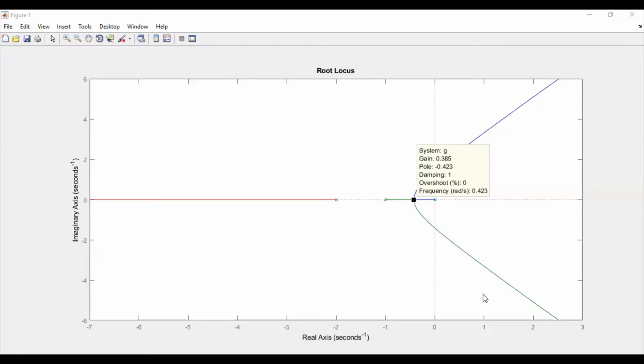Sir, one doubt. In the previous class, while you were talking about it, there are two values of S, minus 0.42 and minus 1.58. So we took the minus 0.42 because there was an overlap on minus 1.58. There is no overlap, no? Not in this, sir. S is equal to minus 1.58, the second case, that we didn't take because that will get overlapped. So that part I will not consider as a breakaway point.